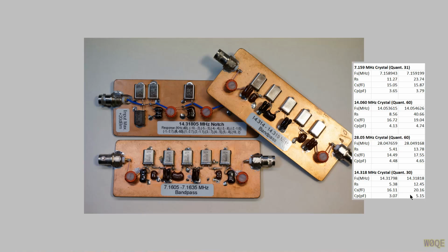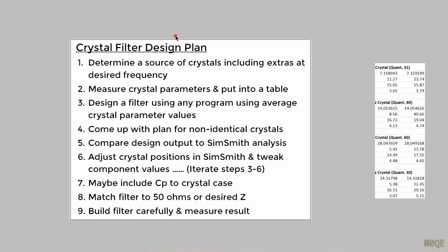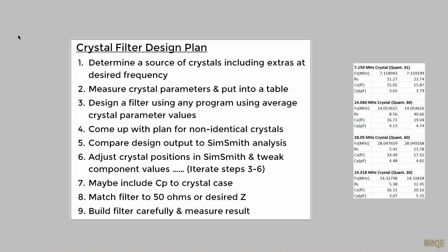And the programs that we use to design a crystal filter typically expect all crystals to be identical. They don't really care what the parameters are, and they'll let you put the parameters in the program, but they almost always assume that, or let me say this, I've never seen a program yet that would accommodate different crystal parameters in different positions. So with having said that, we need to come up with a plan as to what we can do.